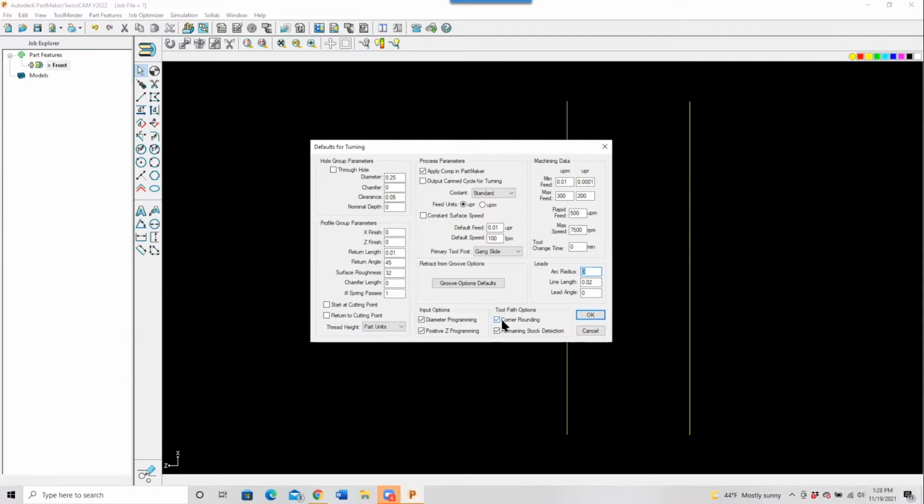Next, corner rounding. Corner rounding is a feature in most modern controllers that allows the tool to move between axes by using both axes at the same time. If I wanted to create a sharp square corner with a clean edge, I want my end mill to transition from X to Z without a pause in the transition from the X to the Z vector. Corner rounding will actually round the corner. It will give you a sharp edge, but the tool stays in constant motion, which gives you a better finish.